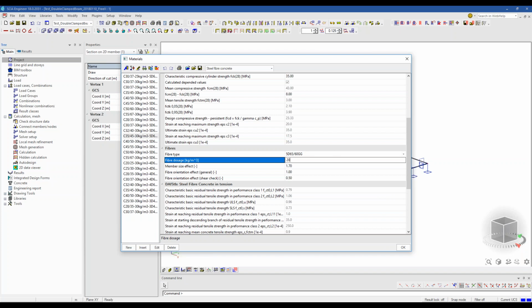What about the concrete cover for the concrete fiber? The traditional method is still valid for it, yes. But keep in mind, if you don't have traditional reinforcement in your cross section, then we will take the full cross section as effective depth.